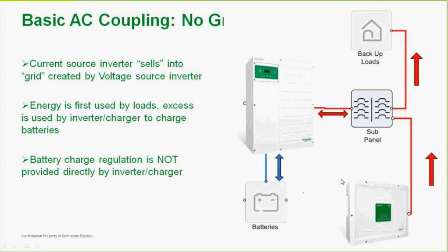It is basically connected to the batteries and will bleed off any excess coming in that is above and beyond what it needs to keep the batteries full. But you have to be careful with that, because the diversion load must be larger than the potential output of this array connected to it. I ran out of room.